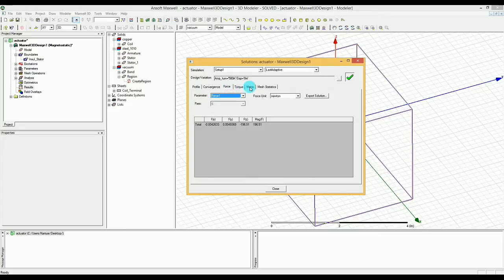You can also check out the matrix here, and you can see that for the current one we have an inductance value in millihenry, and there is no need to select the post processes because we haven't defined any terms. It's just one turn, so it should be the same when you click it. And as you can see, for the current one, which is the coil one, let's make it micro or nano maybe. Yeah, we have 528 nanohenry of inductance. That's the inductance of the coil.